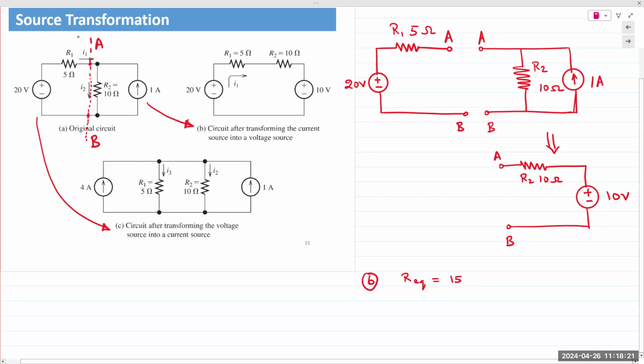And you have two voltages in there, 15 ohms, simply apply KVL. You apply KVL, you get the resulting voltage across that resistor. So you can solve this in one step by applying KVL. 20 minus 10 gives you 10 volts. Left side is higher, right? Right side is lower. So you got 10 volts across that 15 ohm resistor with a plus on the left, minus on the right. That's it, as easy as that.